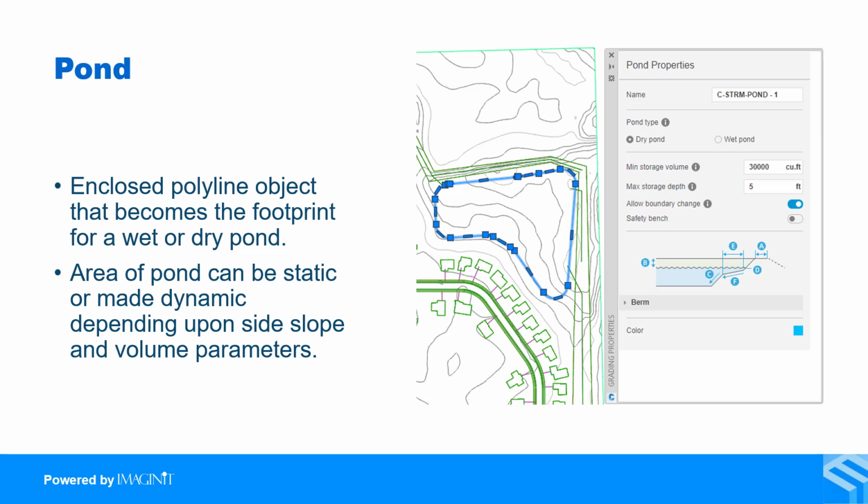I can also add berms. There is additional information. There's the ability to set safety benches for, say, mowing and freeboard requirements to my pond, and it will create the entire grading for me.